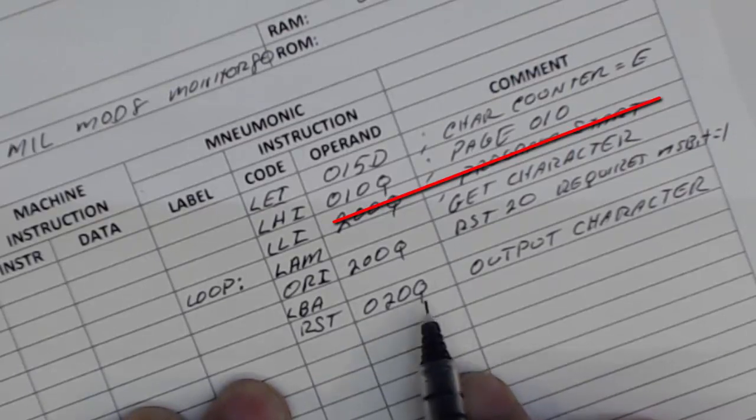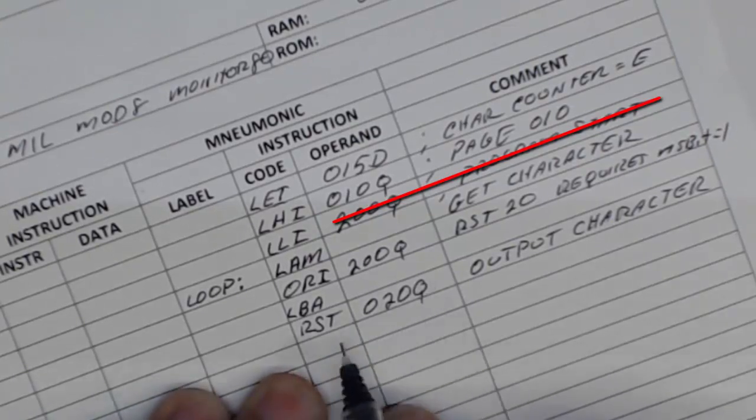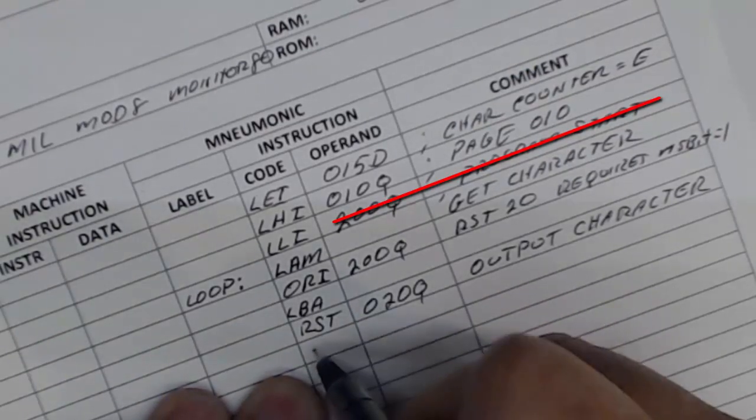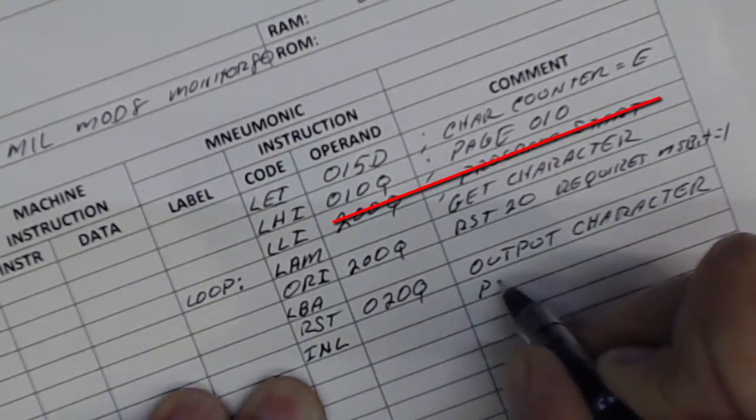That program is going to go to that address, execute whatever code it takes to output that character, and then that code will end in a return of some type, maybe a return or a conditional return. When it gets to that return, it's going to pop that program counter back off of the stack, and that program counter is going to be this instruction right here. So when this is complete, it'll come back to this next instruction. And in this next instruction, we're going to increment the L register, which is our pointer, so it points to the next character.